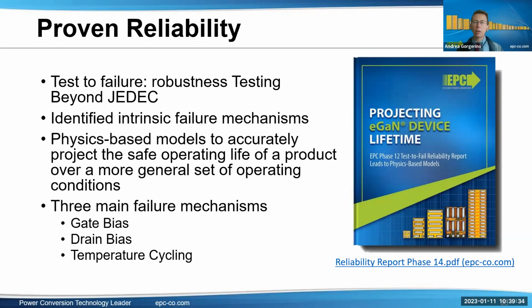There's a whole section on temperature cycling and underfills. We've tested several different kinds. Some actually make the performance better, like the ones I showed in the chart. Some make it worse. And we have some guidelines on how to pick the right one. It has to match the CTE mainly of the board and the device. That's typically the criteria.